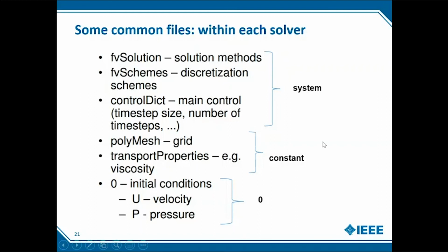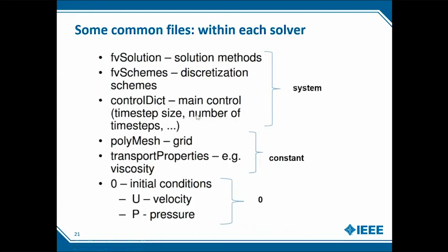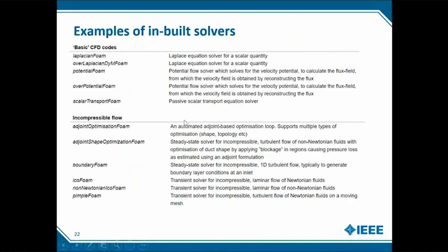So whenever you open OpenFOAM and you navigate to a particular solver, that solver will have these 3 folders, and each of these 3 folders will have these subfiles always present within them. Once you're done setting all of these, you will go ahead and type blockMesh. That will basically generate your mesh, and then you'll go ahead and again press run. That will run your solution.